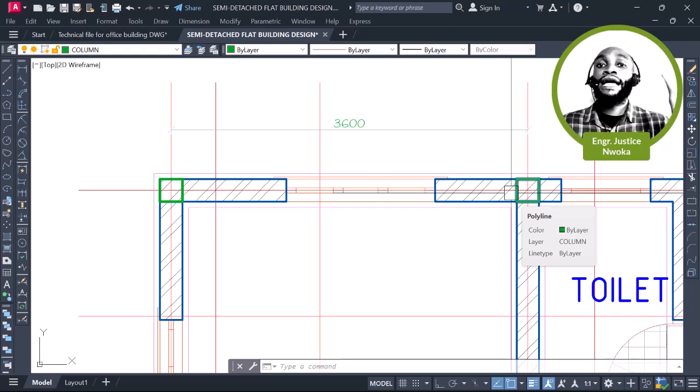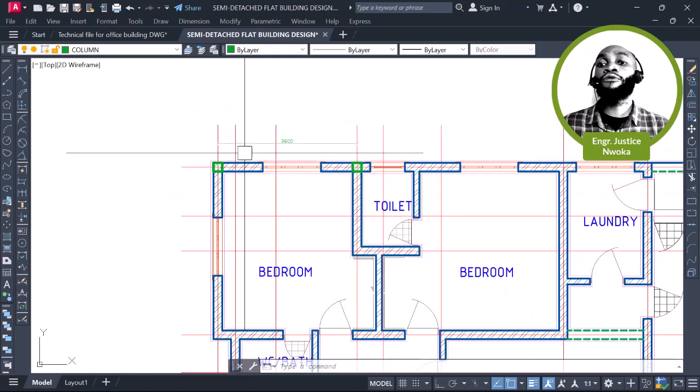And when that happens, your client will be happy, because most clients don't like to see bigger depth of beam, because they don't want to spend money. They want to live in a luxury house, but they don't want to spend money on the luxury house. So just to avoid you as the engineer losing clients, you don't have to exceed your column spacing of more than 6 meters, except there is a chance that the place requires a very large clear distance, and that will now come into experience.